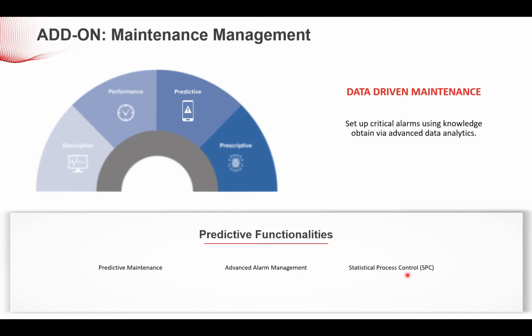So predictive maintenance, or the management interface. Instead of doing your preventive maintenance, predictive maintenance is, when you have access to the data, you can go and decide, for instance, if you have bearings, let's measure the vibration and the temperature on these bearings, and as soon as that changes, either because you have historical data on what it looks like just before they break down, or the manufacturer has supplied you with this kind of information, you'll be able to get this, and then you can set up alarms and say, right, when we start to see this vibration change in this direction, we would like to know it, and then we can do a planned stop Sunday night and change the things before we get into prime time Monday with the whole manufacturing setup with people waiting because the line is broken down.